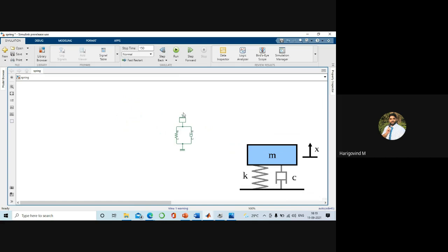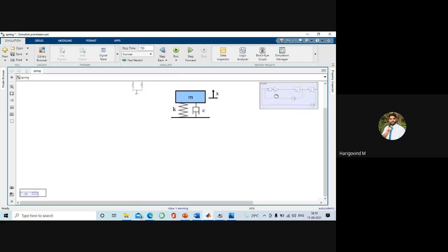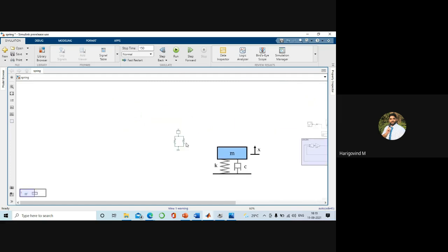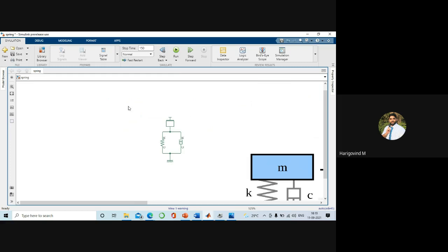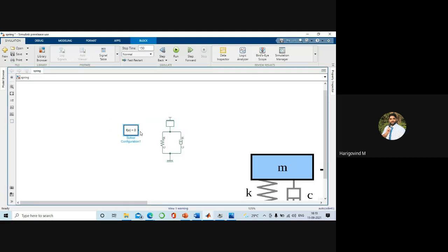If we were solving equations just like we did yesterday, Simulink would directly run them. But as a physical system, every time you work with Simulink and Simscape, you have to add something known as the solver, the tool which converts the physical system into differential equations and helps us simulate.